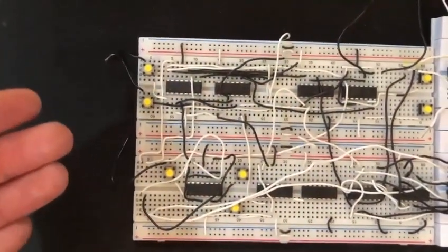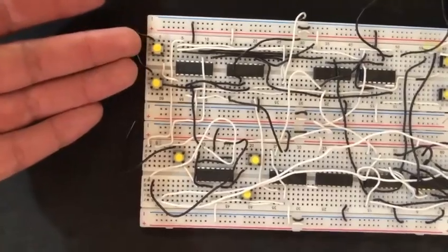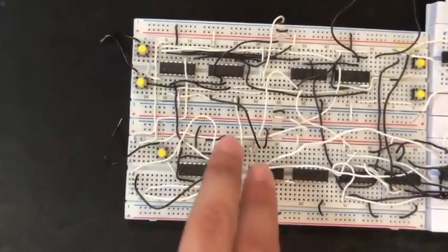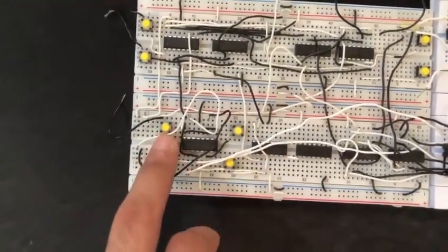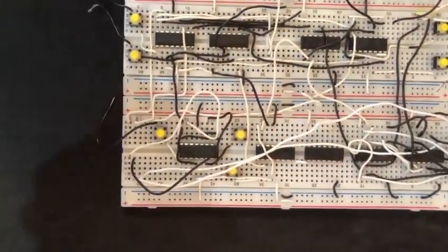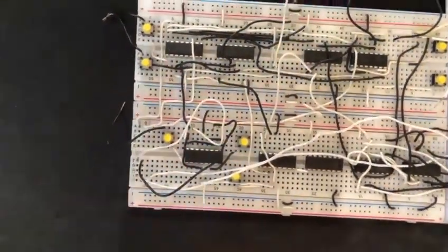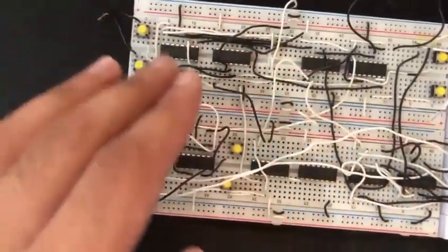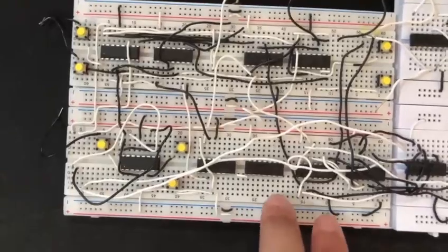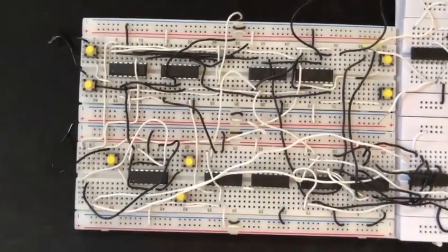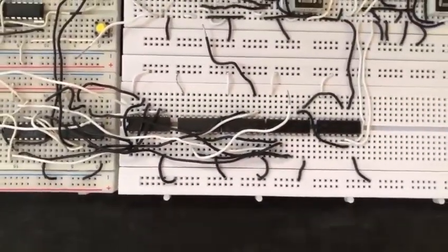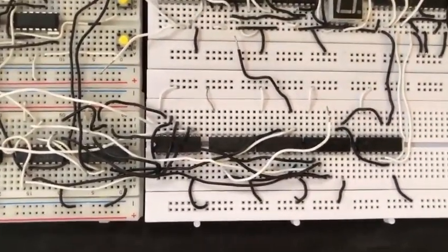After the user inputs the floor which he wants the elevator to go to, he presses the button, and then inside of the elevator, these are considered the buttons that are inside of the elevator usually, and these buttons are then used to send a command to the elevator to either go up, down, or stay at the same floor. These are all JK flip-flops, and the input of the user is stored in these. This is just combinational logic we use to do some calculations on the input of the user. After that, they move on to the directional logic, which determines which way the elevator should move.